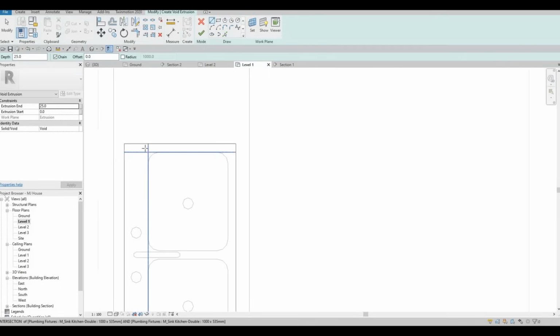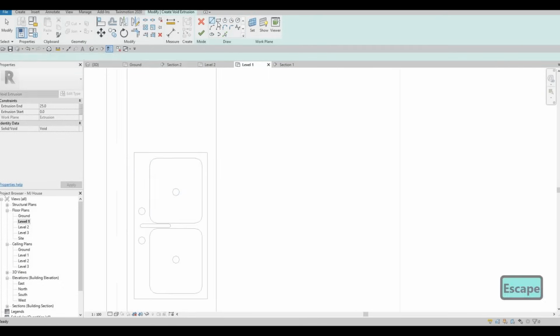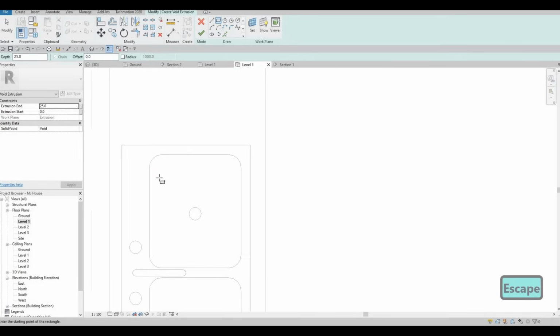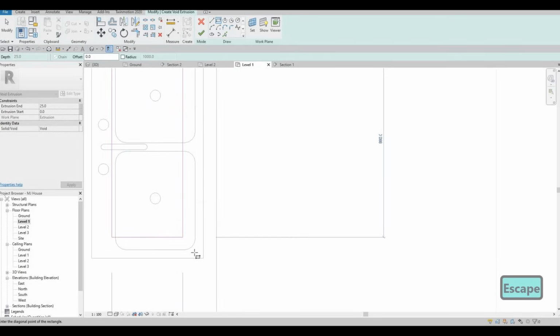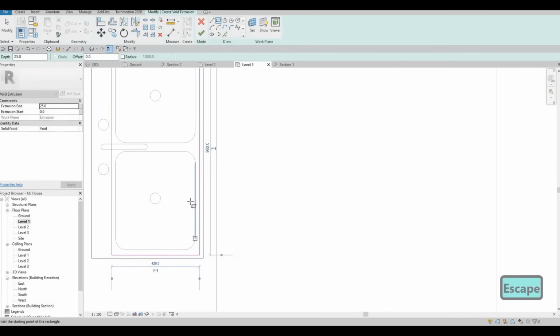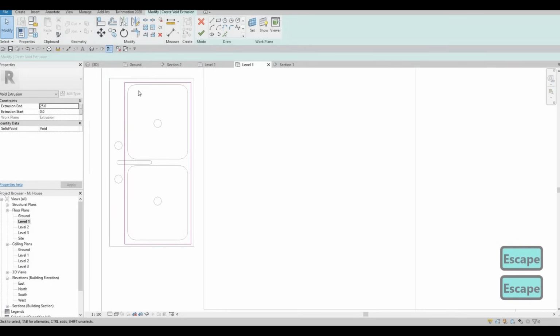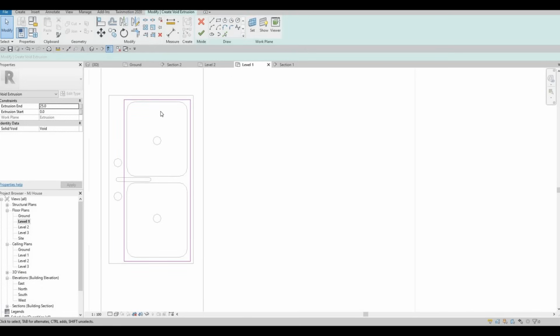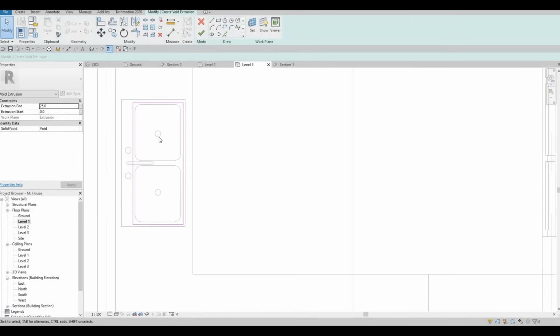And then we're going to create a void extrusion. I usually do this because I want to see the sides of this one, because if you just do it exactly on that, it will have that blinking effect, so stating that there is something there that is overlapped.